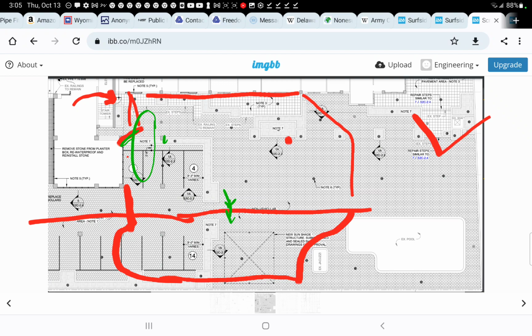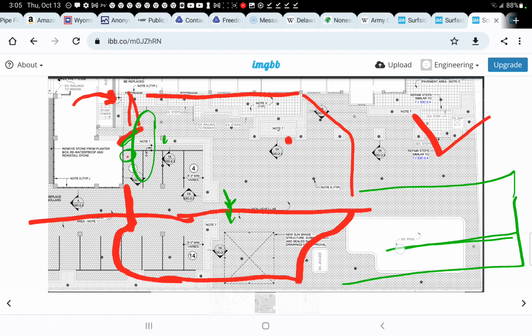Here is our core sample that's delaminating. I mean, there's the rebar. Here's our deck. I showed another video, private room, I think, or Rumble, and I show you how when you get what people like to call shear fracture, we see the bottom steel eject off the concrete from the bottom. Okay, well, in this case, it's cycled many years. I believe what you're looking at is that ejection at the wall.